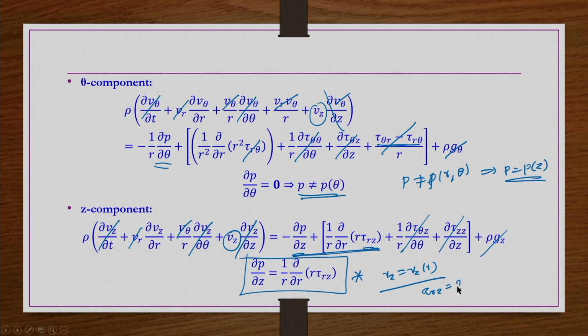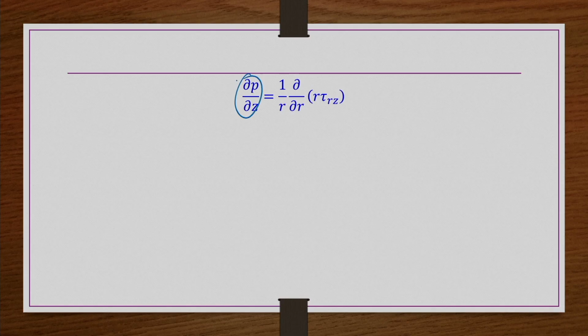So, till now the rheology of the fluid has not been brought into the picture. So, it is a generalized one. The only thing is that the flow has to be laminar and symmetric. Laminar, symmetric, fully developed, incompressible flow should be there. So, what we understand from this equation is that we already realized that P is not a function of r and theta. So, whatever expression is there on the right hand side is not going to affect the pressure. So, dou p by dou z can be treated as a constant.